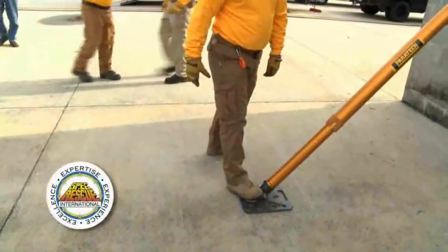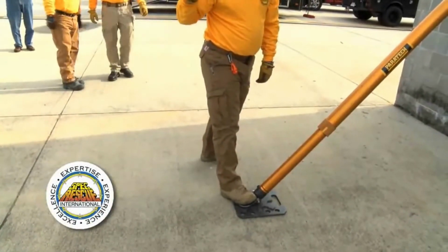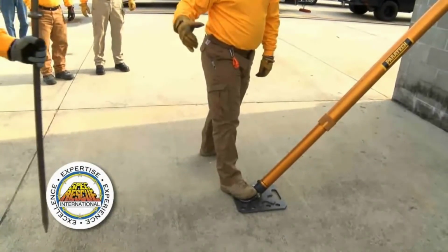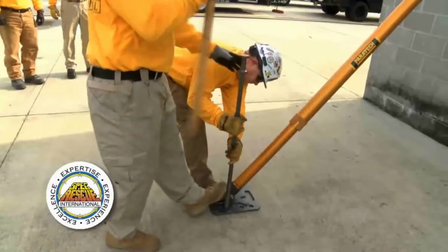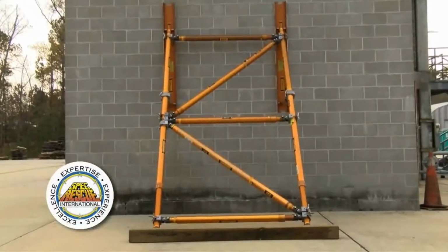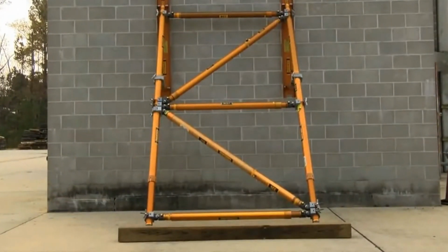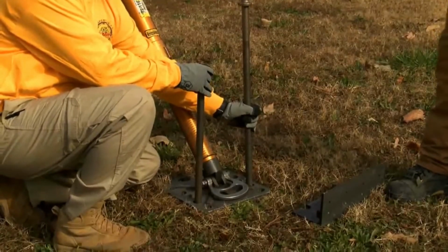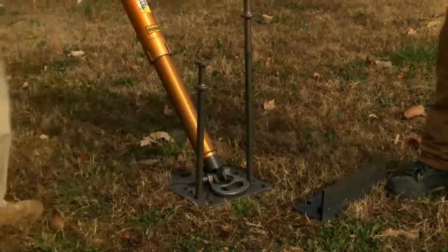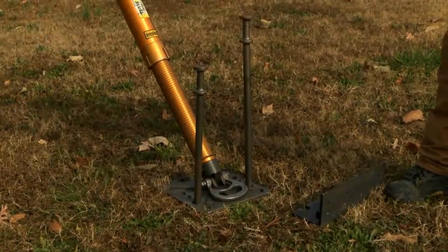Now that we have our raker attached to the wall and the angle is correct, pin the base plate to the ground. Pinning it to the wall will prevent the raker from sliding up the wall if the building starts to move. Pinning it to the ground will keep it from sliding away from the wall on the ground. Pin it with 2 pickets, which is normally the way we start. We can always add a whaler system to the back later.